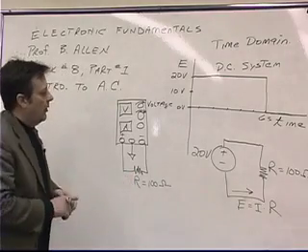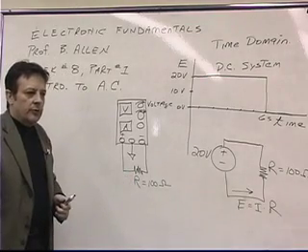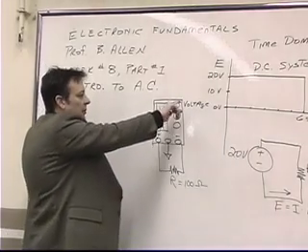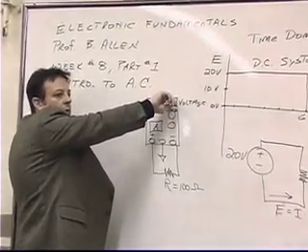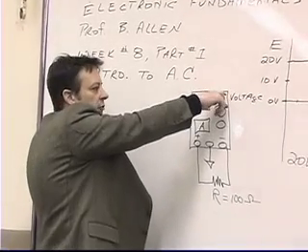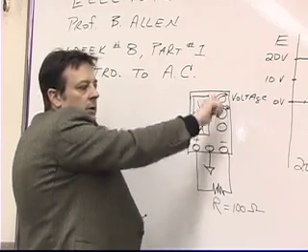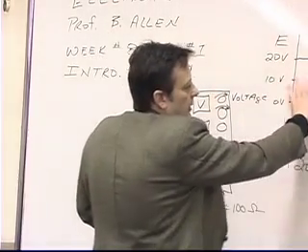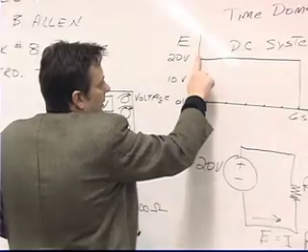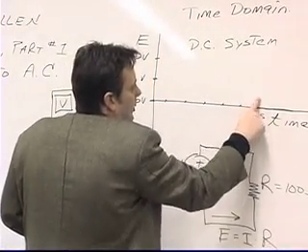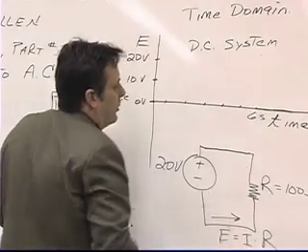One of the team members would be the knob turner. So one of the team members is going to have their finger on the voltage knob, and they're going to start out with the voltage all the way down at 0. So let me come back to the plot on our oscilloscope, and let me erase the waveform, because we're going to have a new waveform now.